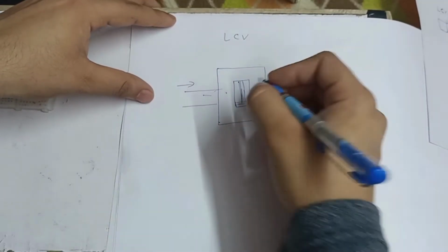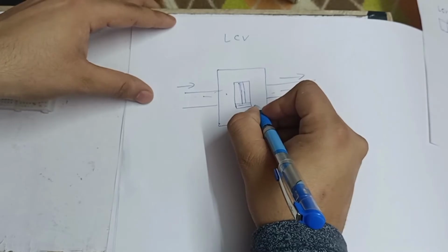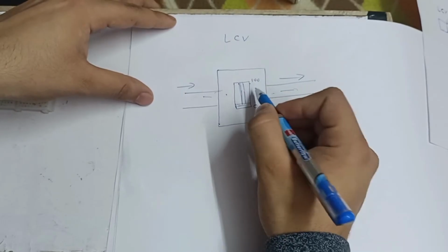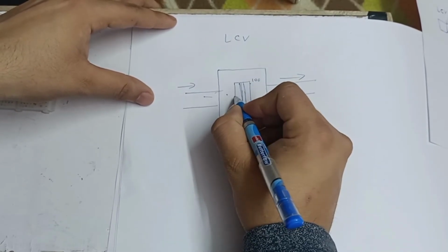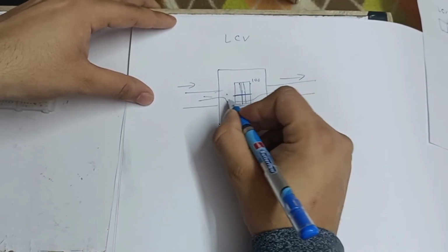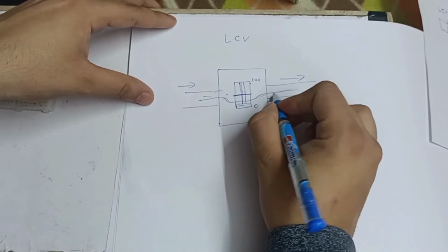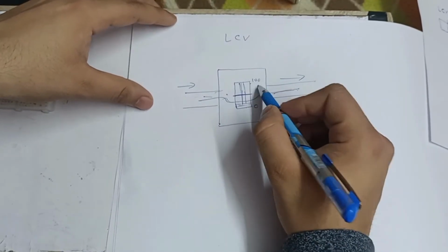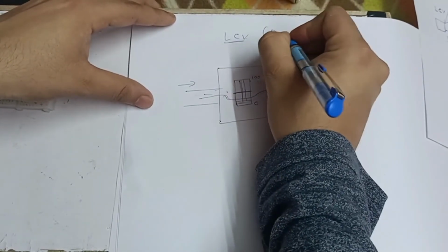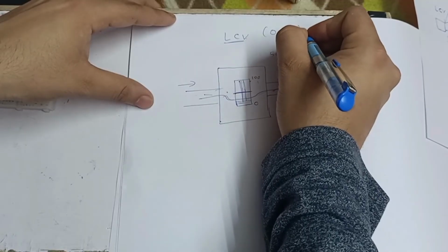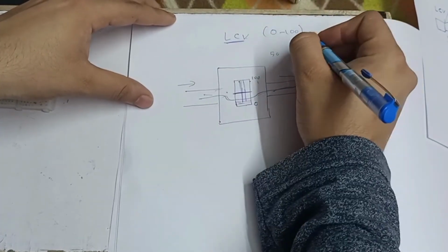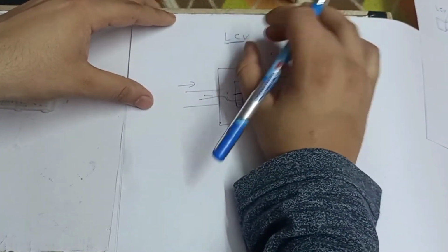When we change from 0 to 100, and we set the value to 50, then this valve is half open, so 50% of the water flows in this area. Not fully, because we set the value to 50 in the LCV, which varies from 0 to 100 to open the valve, like a potentiometer. That is the analog value, meaning it varies as per requirement and we can change it.